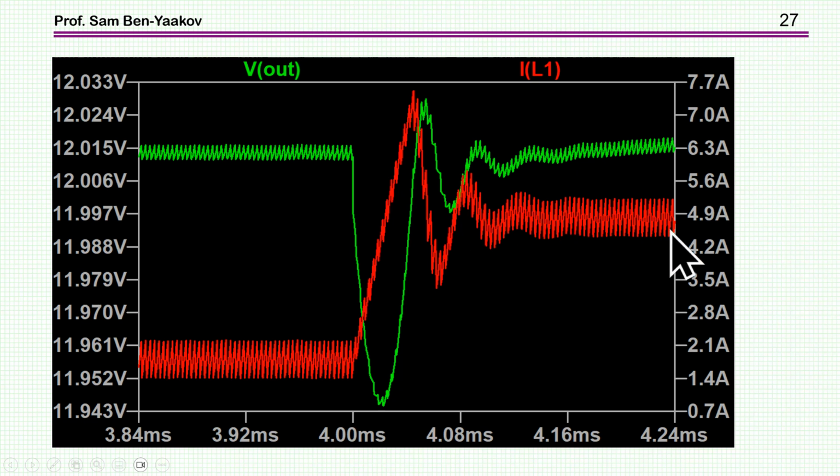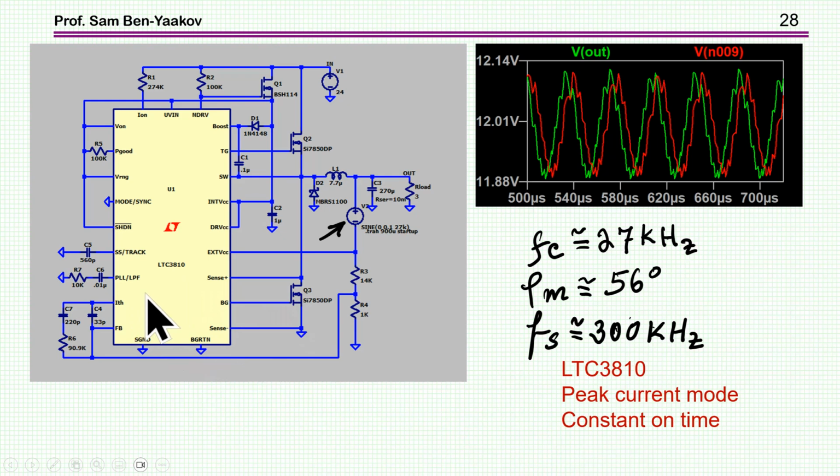This is now the nominal current, and it is now increasing, and then it's oscillating. So you see that this major part here is the slew rate effect, which has nothing to do with the second order behavior.